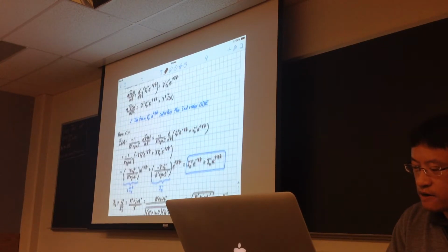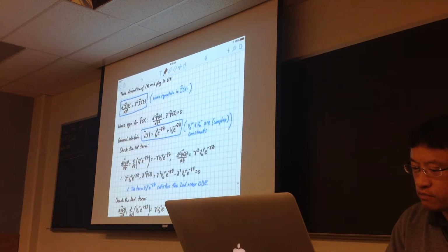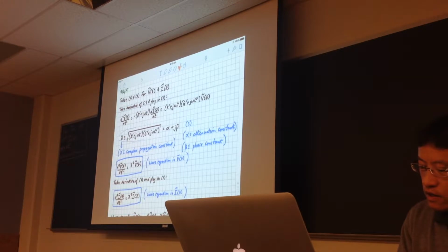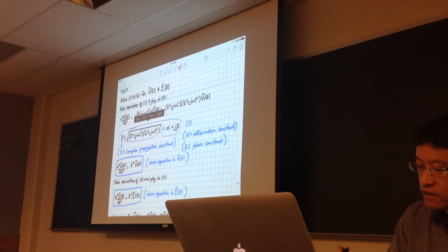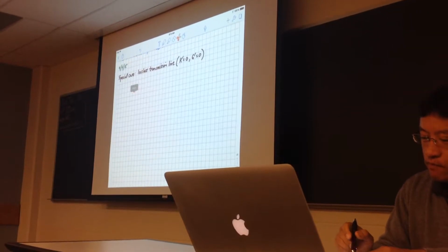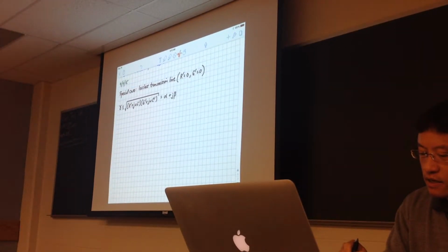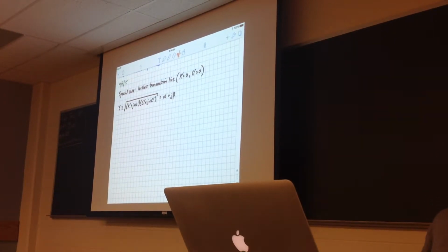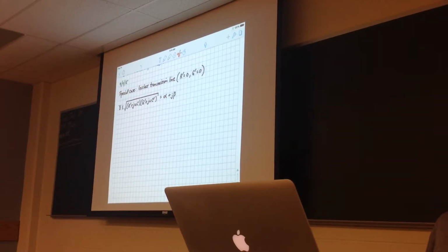Let's take a couple of parameters from last time. If we look at our complex propagation constant, I copied it from last time, and I'll give you time to write it. So the complex propagation constant, gamma, we found in general to be the square root of (R prime plus j omega L prime) times (G prime plus j omega C prime). And since it's a complex number, we can write it as alpha plus j times beta.